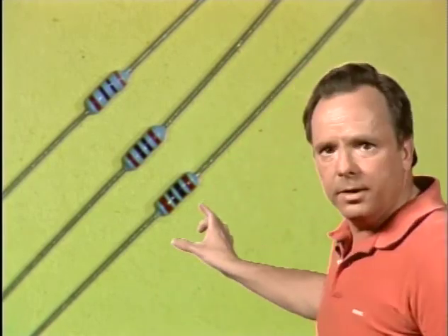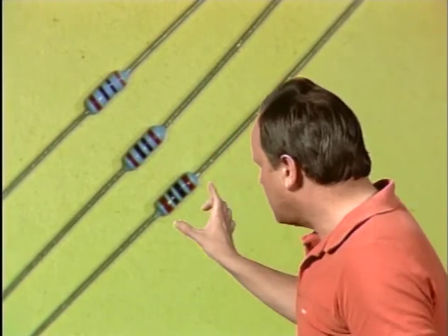And resistors are generally classed as fixed or adjustable or variable depending on their construction and use. And a typical fixed resistor, like this one, consists of a small rod of carbon compound. So here's a typical fixed resistor. Now, an adjustable resistor is usually a small wire-wound type with a metal collar that can be moved along the resistance wire and it'll let you vary the value of resistance placed in the circuit. And a variable resistor is arranged so that it can be changed in value any time by the operator, generally a knob. And variable resistors are commonly known as rheostats or potentiometers.